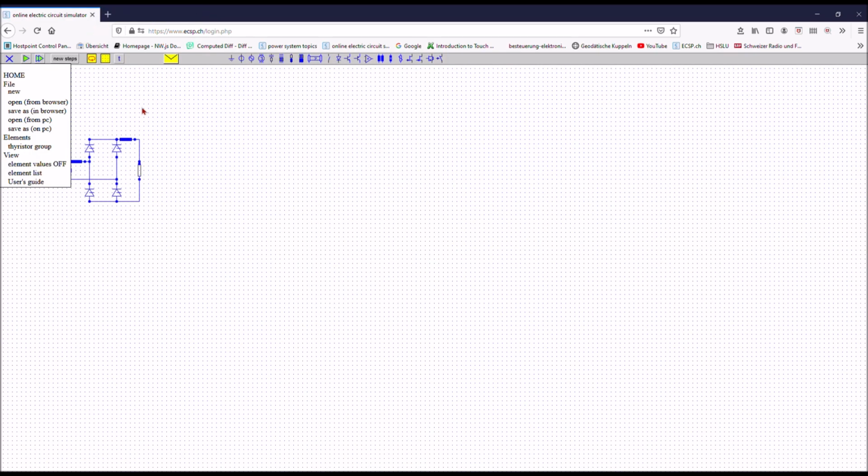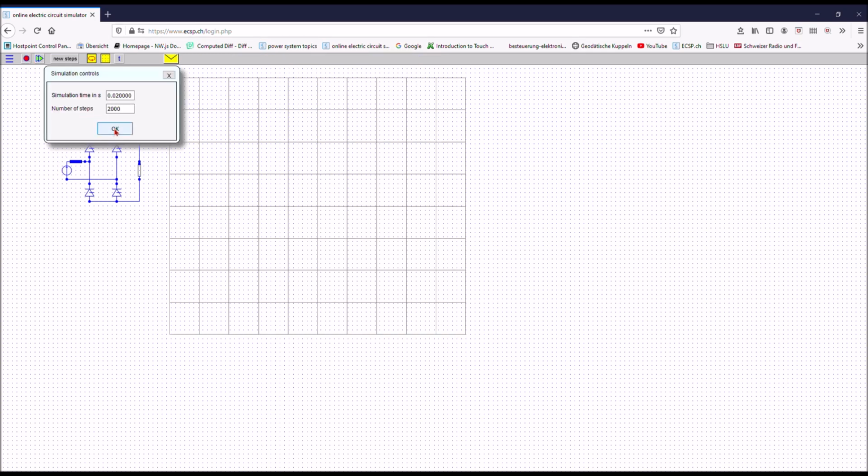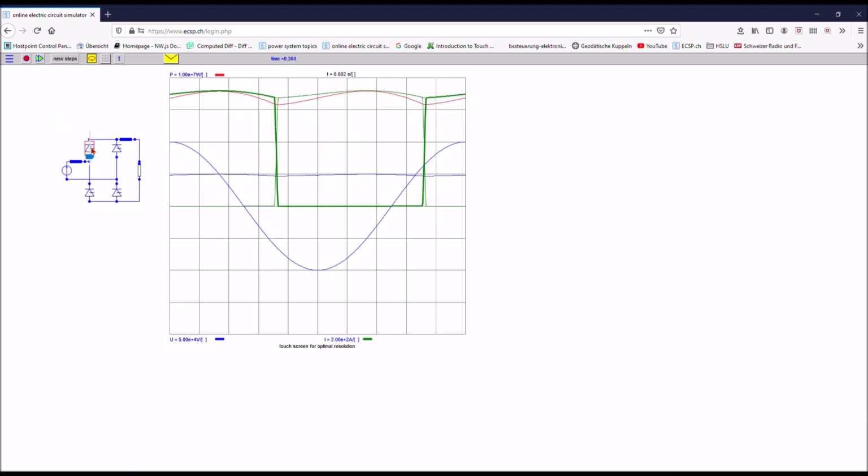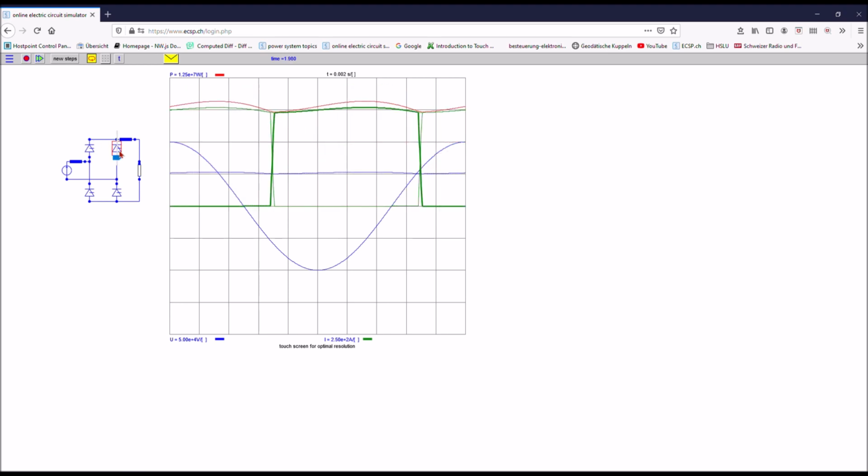First of all, you have to set up a reference for all the thyristors, preferably the source, and then you have to group them all together so that you can control them as if they were one. So you can see just shifting one shifter controls all the thyristors, so they have the same position of all the shifters. So that's the magic of this program.